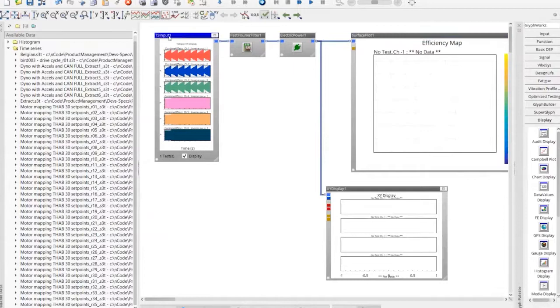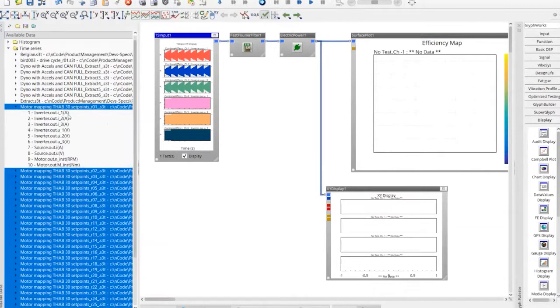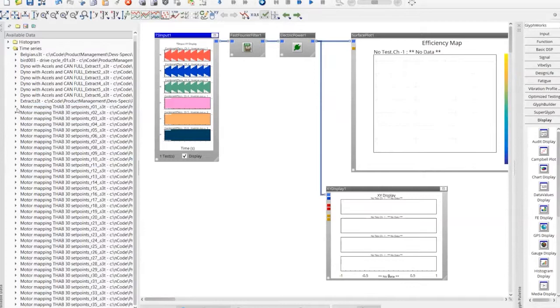So I've got in input a very large time series, which actually is the concatenation of I think it's like 35 snapshots, each lasting like a minute or two at a very high sample rate. And in each of those, we have the three-phase current, the three-phase voltage, the continuous current and voltage out of the battery, and the speed and torque of the shaft of the motor, right? So, and we've done snapshots at various speeds and torque on a test bed, right?